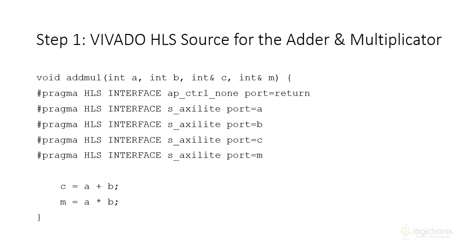So you already see that link. And we have the ports instantiation for the AXI-Lite interface. So A, B, C, M are instantiated for different ports, and all the unnecessary ports are dropped. The first line will drop the other ports which are not necessary for us, like the basic interrupt and other things.